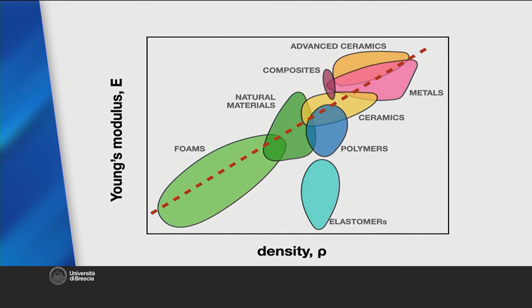The dashed red line is therefore a sort of close relationship, valid for most families, between stiffness and density. However, some families of synthetic materials try to break out of this kind of valley. To improve stiffness without increasing mass too much, lightweight and strong reinforcements can be introduced, such as carbon fibers. On the other hand, by introducing voids into the material, as happens in expanded materials or foams, you get very lightweight materials, although with a reduction in stiffness.